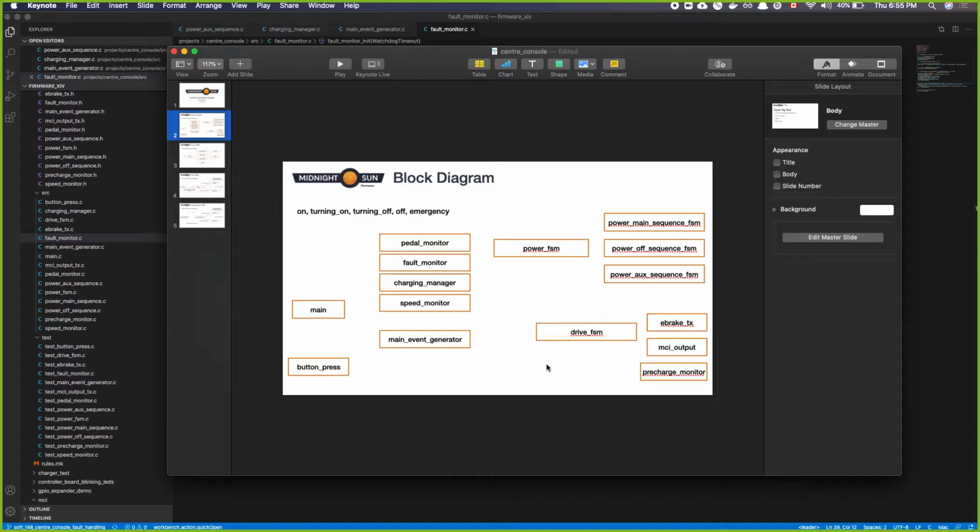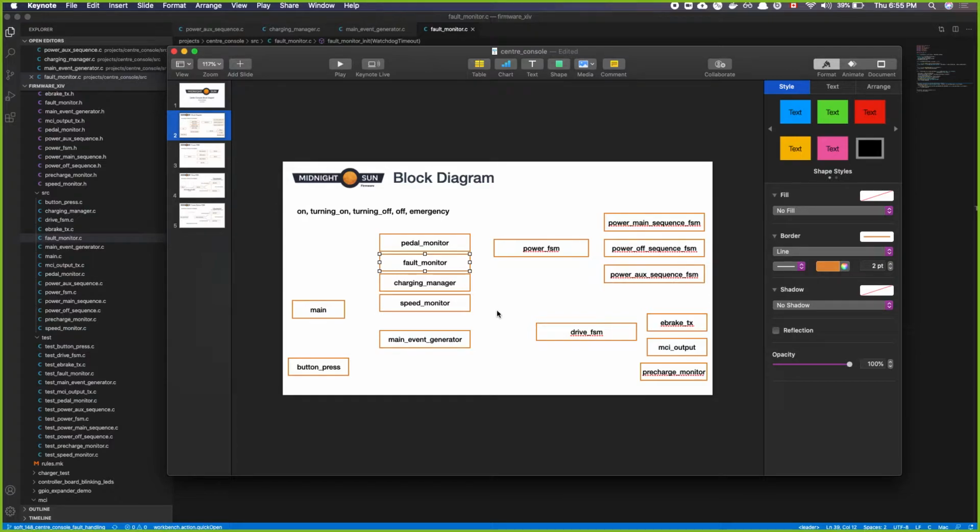So the battery can have a battery heartbeat message, in which there is a bit set, and each bit corresponds to one specific kind of fault that could potentially happen, right? So over voltage, under voltage, temperature, AFEs, if one of the AFEs faults, or anything else. And that will set that one bit, and it will send it. This fault monitor constantly checks for the battery heartbeat messages, and if the heartbeat is okay, it will clear its own faults if it previously had any. But if anything is not okay, it will set its own status as faulted, right?